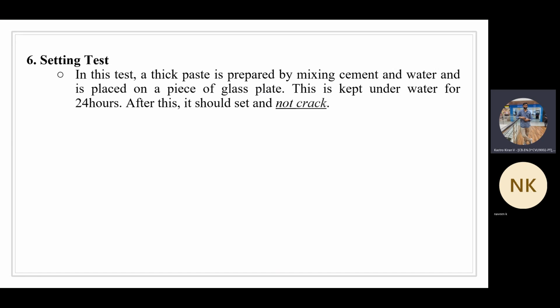After 24 hours, you should find the cement has set and does not have any kind of cracks. If cracks are available, that means that cement is not a good quality cement. And the last test is called the strength of cement test.